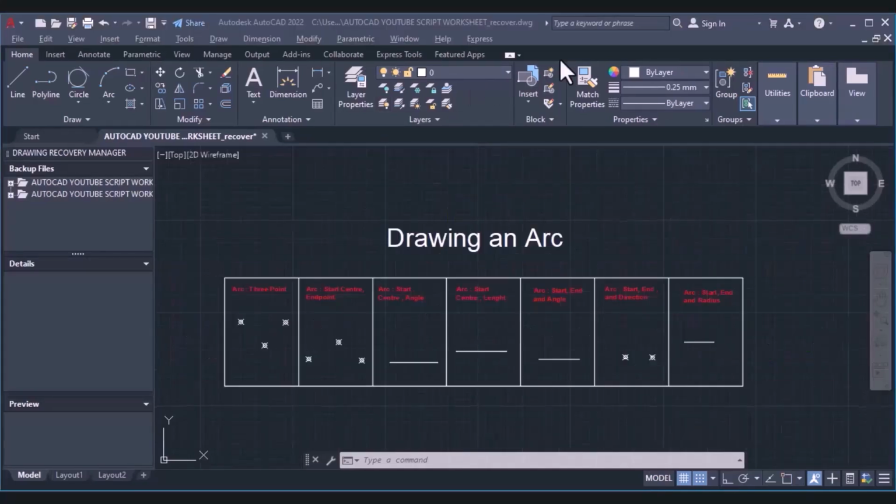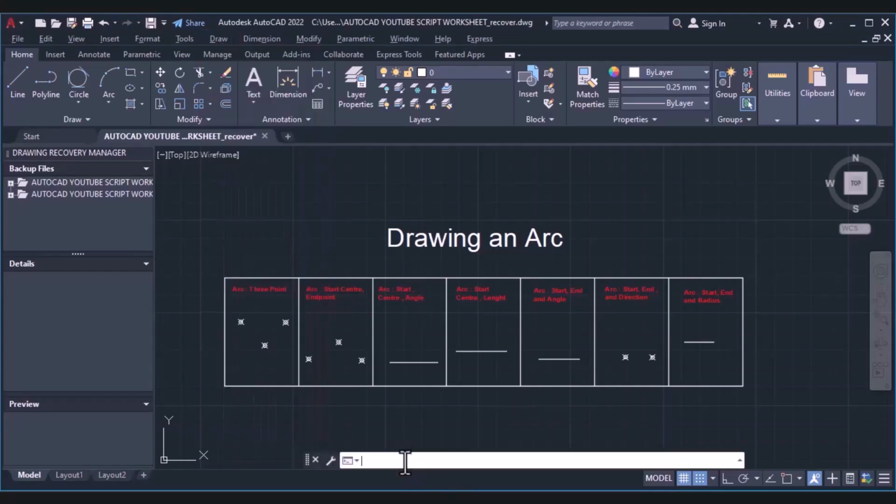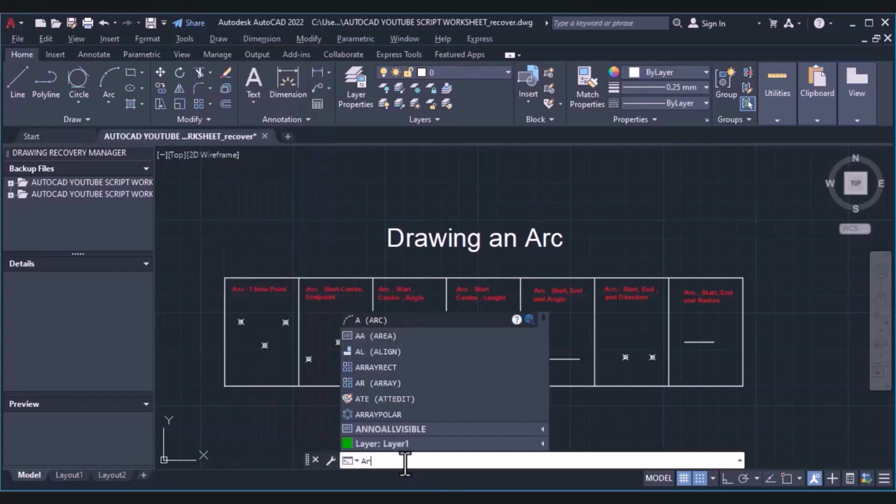So next thing we are going to look into is drawing an arc. Now the arc tool is found next after the circle tool. We already know that the arc is the half section of a circle. Now to activate the arc tool, either we click on the draw command group, you can see the arc icon here, or we can go to our draw tab on the menu bar, click on it and locate our arc. Or we could simply search our arc here, type the keyword and notice it brings out the arc action. So either of these can be used to input or insert the command.